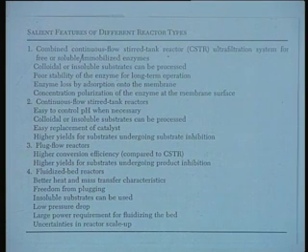Now, in the case of long-term operation, one is that the system undergoes a very fast rate of deactivation, mainly because you have to transfer the whole material along with the substrate into the ultrafiltration module and recycle back the retentate. So during all that transfer, there is significant loss occurring. And as a matter of fact, you must also appreciate that one of the reasons of inactivation is also shear inactivation.